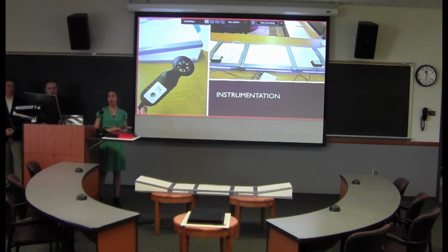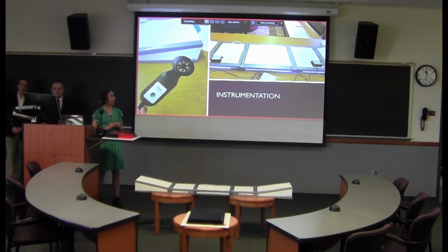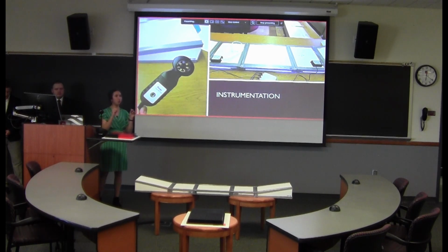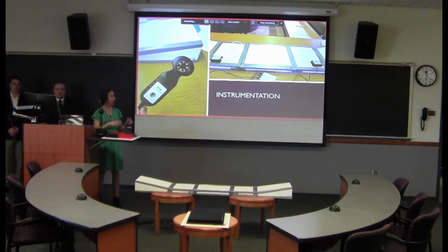There were basically three things we were asked to measure. We were asked to get pressure drop, obviously, air velocity, which would allow us to calculate CFM, and then to get an ambient temperature reading as well. So to measure the pressure drop, we have two barometers, one on each side of the testing chamber. You can see them in that picture on the right. And as you can see, we don't have them right up against the edges of the testing chamber. We have them spaced about 4 inches out. Again, that's to hopefully get them out of any weird vortex effects and just get them in straight flow. So we were able to measure pressures there and take the difference between them to find the pressure drop.